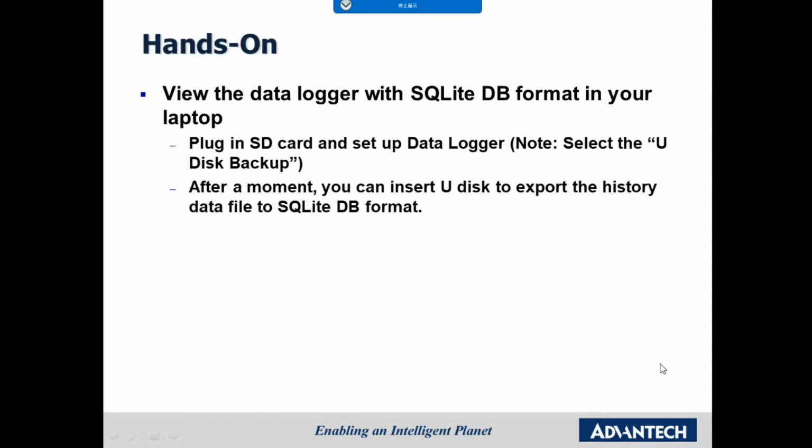Hands-on. Please view the data logger with SQLite DB format in your laptop. Hint 1. Plug in SD card and set up data logger. Note, also select the U-Disk Backup. Hint 2. After a moment, you can insert U-Disk to export the historical data file to SQLite DB format.